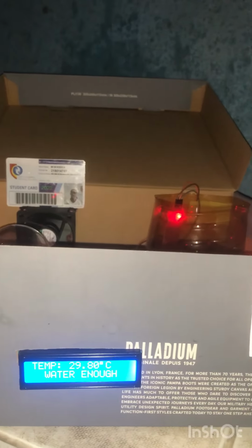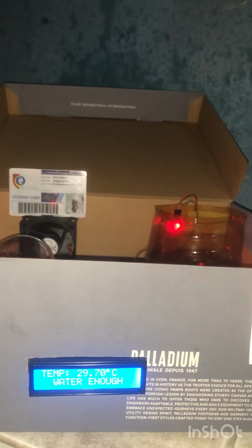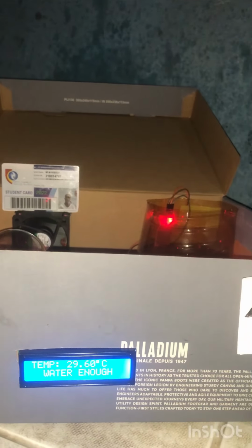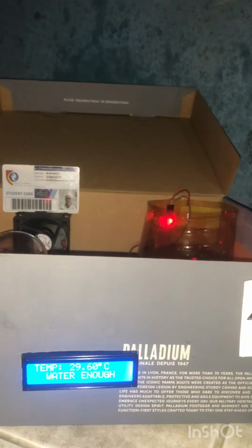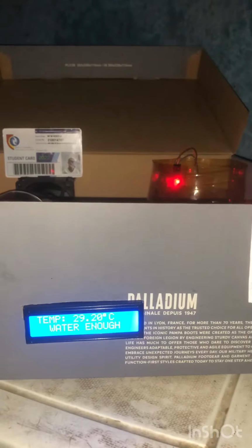So now the temperature is supposed to drop steadily, and as soon as the temperature hits below 29 degrees, we will go back to normal mode. And remember, back in normal mode, our cooling system is supposed to be off, our heat source remains off, and our window will be slightly or partly open. So no control mechanism other than the window being slightly open will occur.